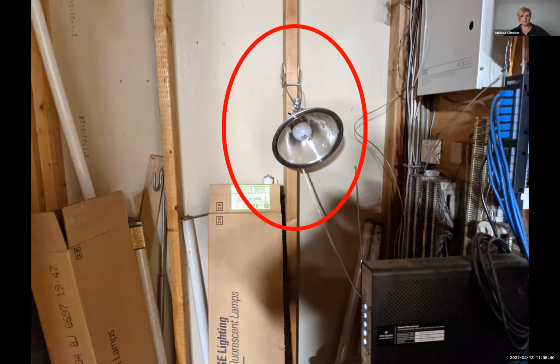Tim, you want to talk about this nice lamp? This is one of my favorites, the task lighting. As I always say, when I find these things, it says, give them to somebody you don't like. Well, no, that's just kind of a joke. But you look at that electrical light, there's a lot of hazards there. The bulb isn't protected. The outside shell on that, if you've ever used one or had one, is not real secure. It's not grounded. It's a 2-prong plug on it.